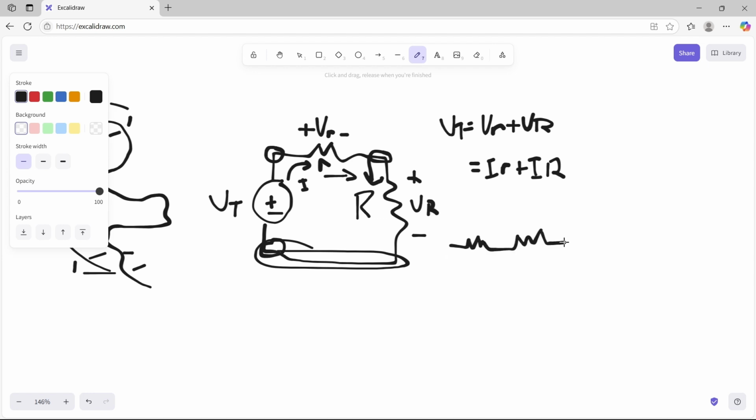They must receive the same current. Now, there is a different scenario: what if we had these two resistors in what we call parallel? Well, suddenly whatever current is passing into this first node doesn't necessarily equal the current passing through both resistors, but importantly, it does equate to the current that passes through both nodes. So whatever comes into here on the left side must exit on the right, but between these branches it may